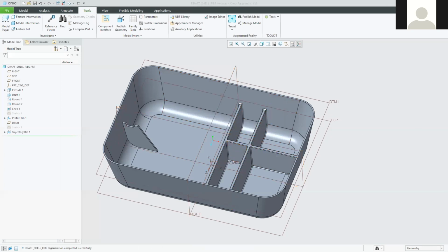So that's the first bit of what we've done. We've tied them to a parameter that we can then refer to control other features. So we could use it to control the thickness of the box as well, and the thickness of this rib as well. This way we're tying them all to a single value. So if we make that decision that they must all stay the same, the easiest way to drive them all is to edit them all at a central place, not to go into each feature individually and edit each one individually. So where are we going to go next?